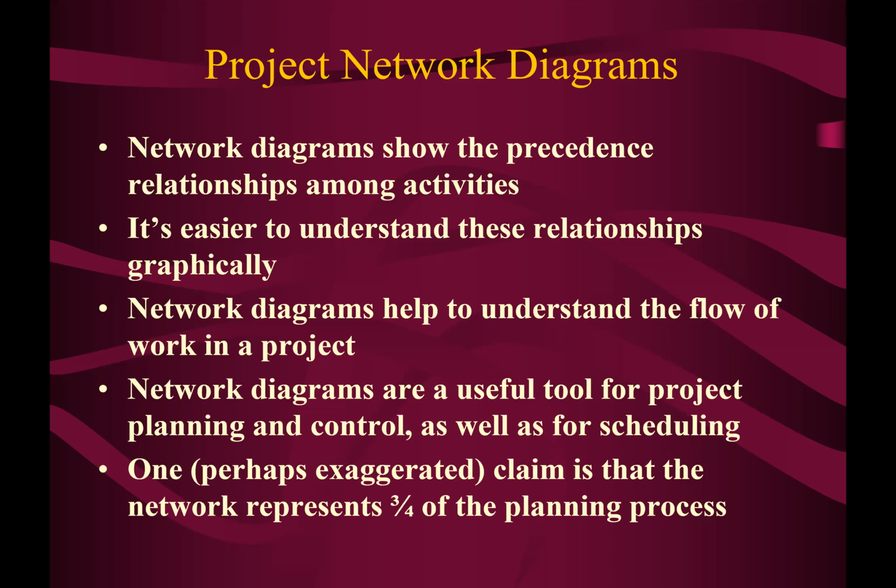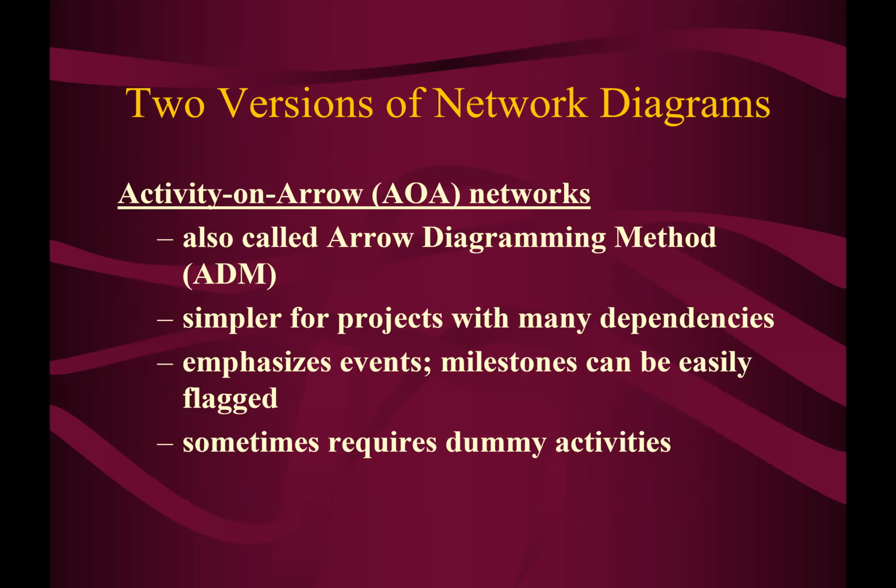Why? Because we want to see the impact of delay. If one activity is delayed, what could be the impact to the next activity or the following activity, or even to the overall project duration? So that's why we develop our work program in a network diagram. In terms of network diagrams, there are also many types available as scheduling techniques, even using different software.